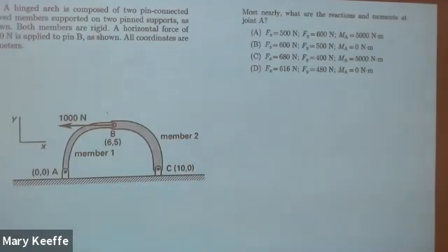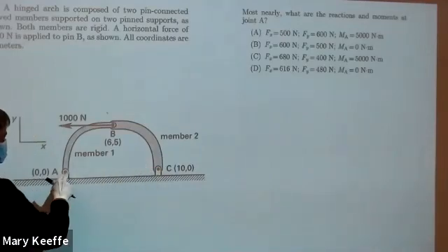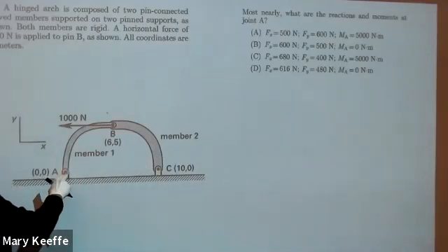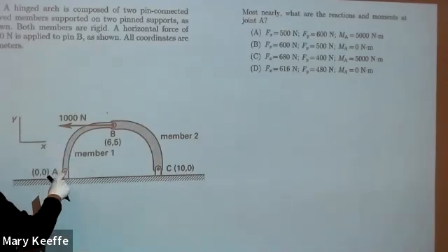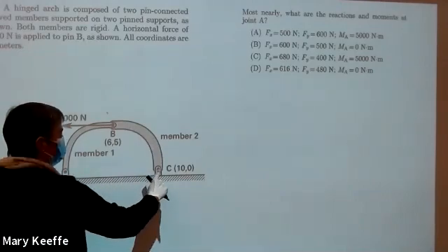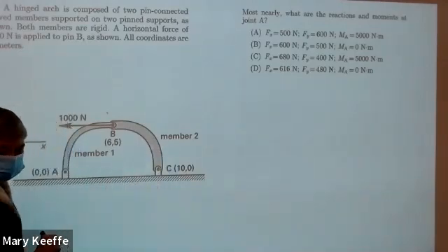What we have to remember is that we can take things apart. So here we have this hinged object and it's pinned at 2 points. So remember, pins are going to exert a horizontal force and a vertical force. So my support reactions would be a force up and this way and up and this way.